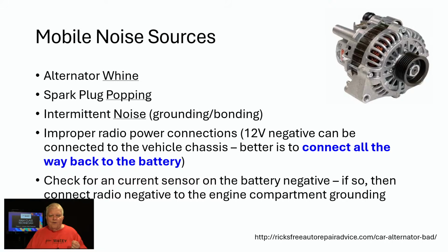It may work briefly, but you'll get lots of noise, and so you want to run the power leads all the way back to the battery. Or if your engine has a current sensor, you want to keep that in mind. Maybe consult with the manufacturer. So batteries in the car, noise sources in the car.